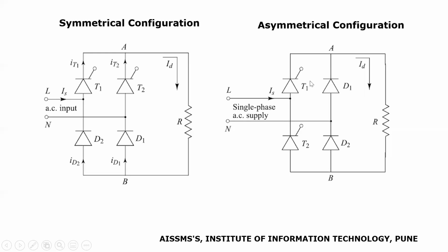In asymmetrical semi-controlled converter, one arm of a bridge rectifier consists of control switches and second arm of a bridge rectifier consists of uncontrolled switches. The cathode of thyristors, which are acting as control switches, are connected to different potentials, and hence in asymmetrical converter we need two separate triggering circuits to provide triggering pulse to these thyristors.